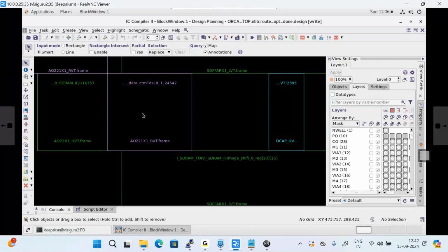There is also full custom layout. The role of full custom layout is to see the schematic, how the design is done, and then draw the layout. Full custom layout is easy. But full custom design is complex, very complex. Then you have to learn the concepts of MOSFETs and mixed mode signal analysis. So how this op-amp gain is dependent, it depends on what parameters. Op-amp bandwidth is dependent on what parameters. How to change the bandwidth, how to change the gain, how to use different W by L ratios, how to do biasing. Biasing means applying DC voltages for amplifiers. All those concepts you have to learn for that.